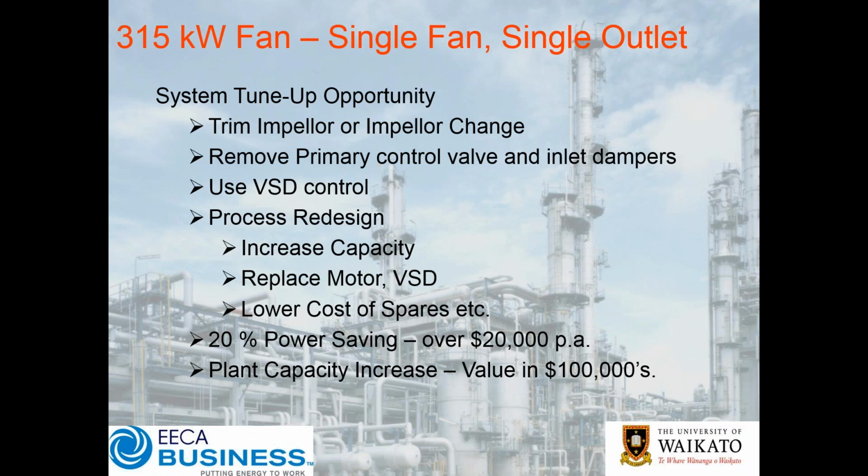And likewise, if you're looking to change the width of the impeller, often that would be a straight impeller swap as well, as opposed to physically taking the impeller out, mounting it in a lathe and machining a bit off. Obviously, axial fans are slightly different in that you've got to start thinking a little bit more carefully about the whole shape and design of the blades and so forth.